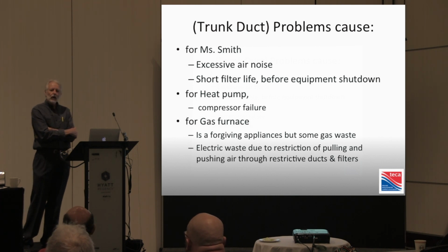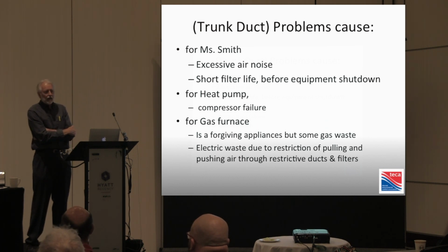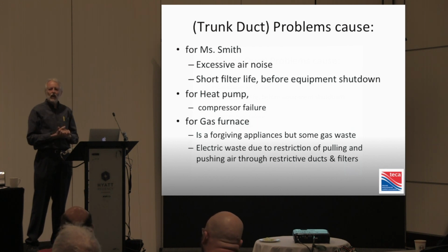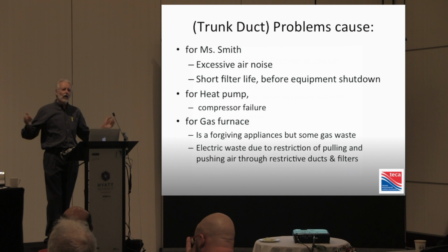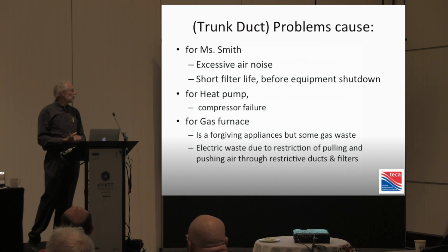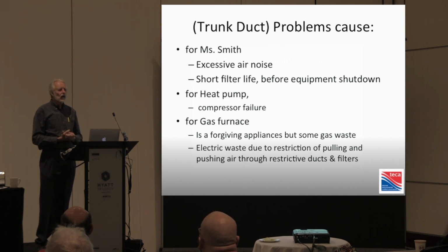If you take the compressor out because it's failed, they send it down to Tyler, Texas, the techs take it apart, and they can see by taking it apart whether it's seen what we call a high head pressure condition. And a high head pressure condition will often result from inadequate ductwork, because if you can't take the heat or the cool off your indoor unit, that thing works harder and it can destroy itself in the pursuit. Okay, well, no sweat at all, that's the sub's responsibility, but it's going to end up biting you in the ass, because if you smoke a compressor, you contaminate the refrigerant system which it's operating in.